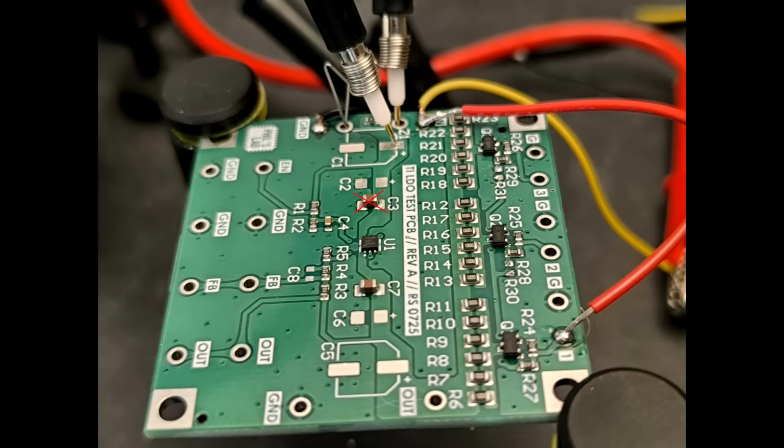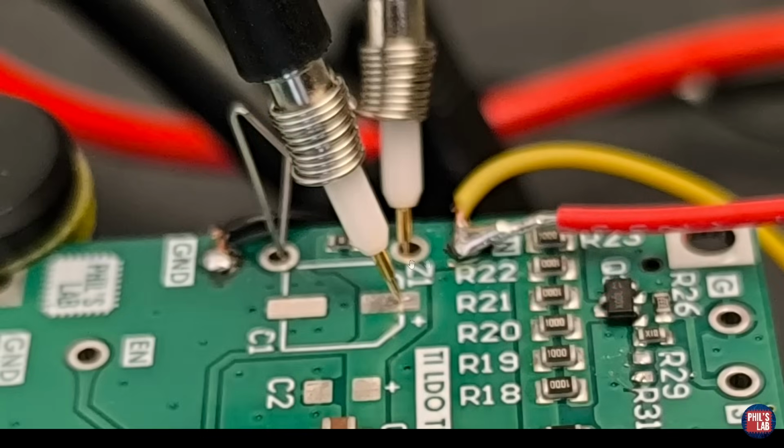These are the connections we have initially for our calibration. I've attached channel 1 to the input of our test board and channel 2 of the Bode 100 input also to the input of our test board. In this way, we can nullify or cancel out any imperfections or non-idealities of our cable and measurement setup, so we have a null output before we perform the actual PSRR measurement. So we need to calibrate our system before we can perform an accurate measurement.